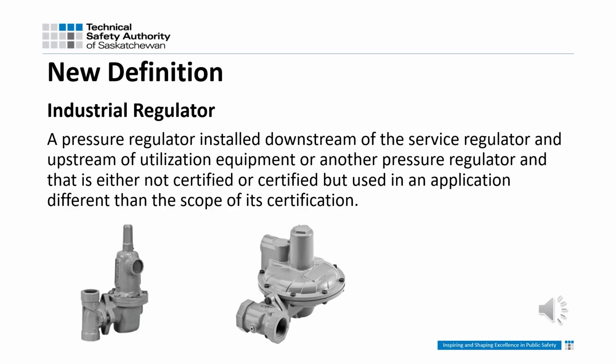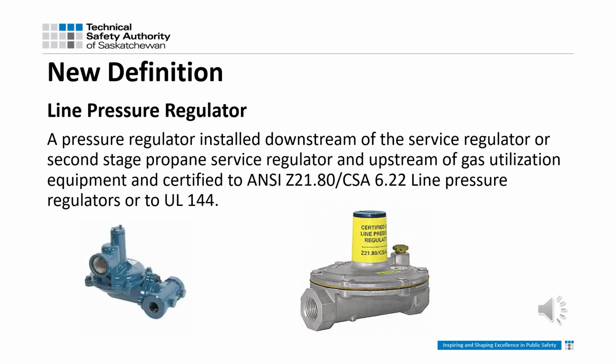This definition is to show the difference between an industrial pressure regulator and a line pressure regulator, which is our next slide. A line pressure regulator, by definition, is one that is certified to CSA 6.22 or to UL 144, and so this definition was added. When installing these regulators, it is important to read the installation instructions for all the manufacturer's requirements to meet certification.